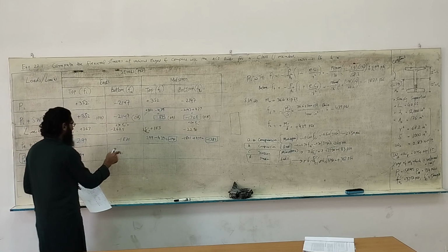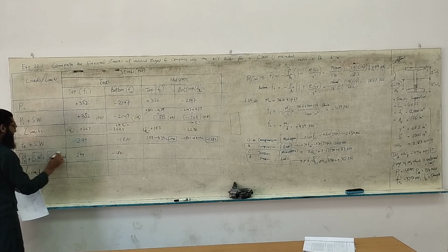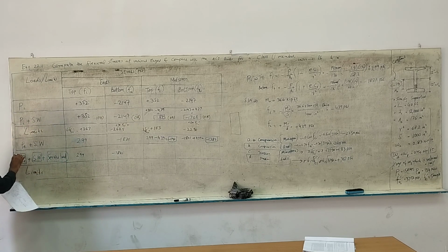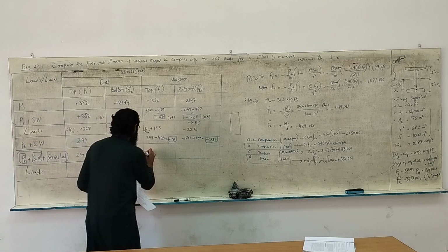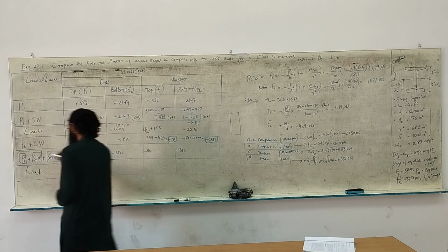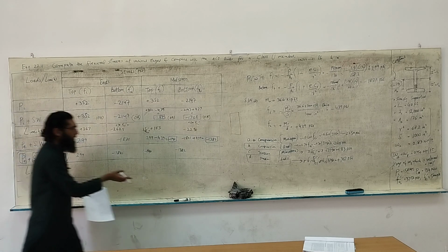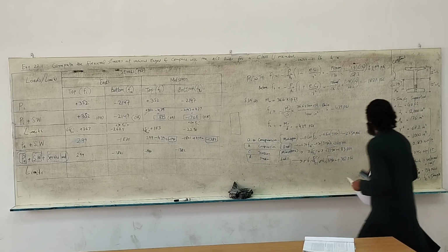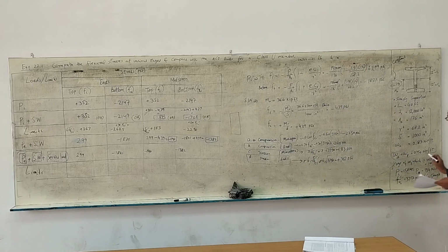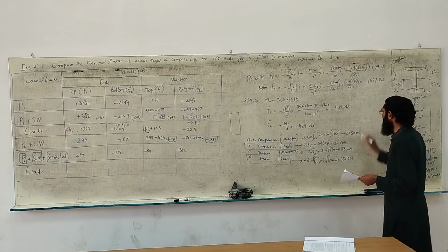Okay, now what about the midspan? At the midspan, all these together will have to be considered. So we've already taken care of this part over here. So we'll have minus 140 and minus 1382. These are due to these two, and we need to take care of the service load now. For the service load, okay, we have 0.750 kip per foot. So we can calculate the moment.